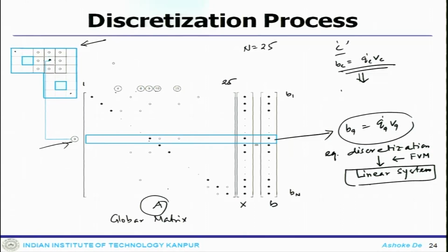Now, what can happen? Typically, this matrix that you are getting does not necessarily have to be very smooth, because once you talk about the Navier-Stokes equation, they are not going to be smooth. It could sometimes be sparse, it could sometimes be banded; it depends on the particular PDE that we are solving for. So, in a nutshell, when you solve a realistic problem with the Navier-Stokes equation, this A is essentially a sparse large system.